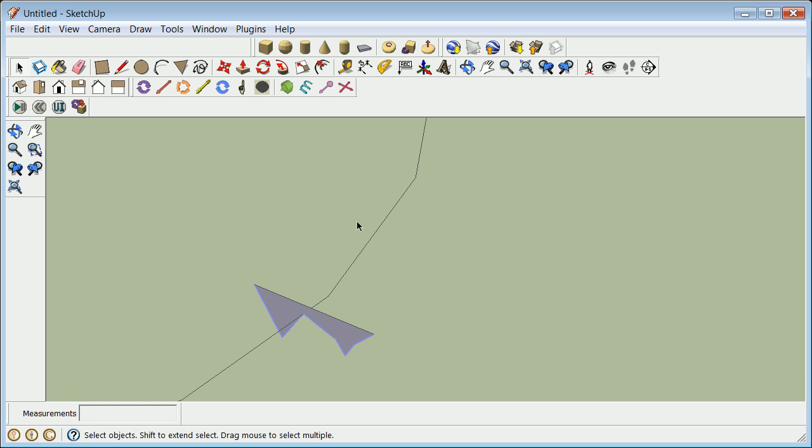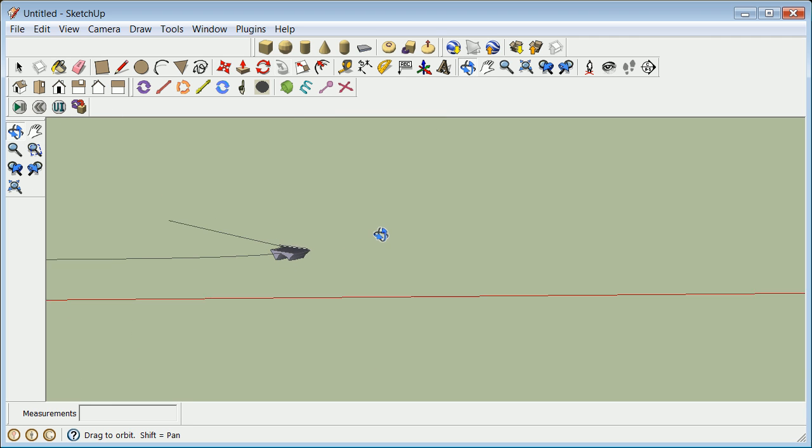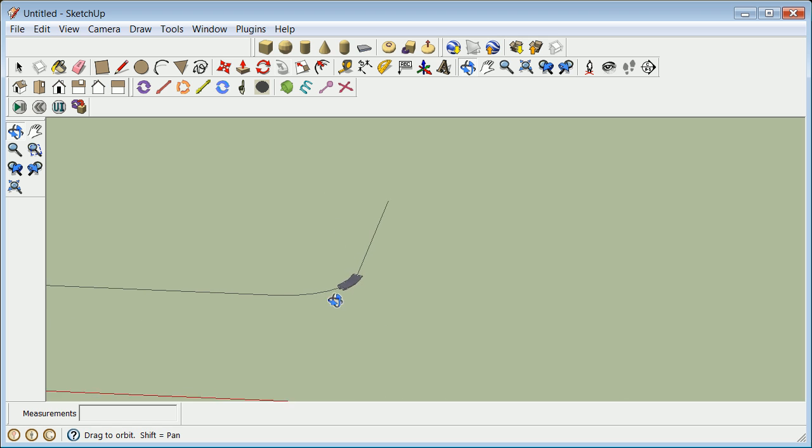and immediately that finds the face, and we're just going to see whether this thing works. I grab that tool there, and then I hit follow me and click that, and you see that it will design at least part of that road section. Alright, and that's typically your extrude or whatever else. Right, so what you'll see in that is, I'm showing you this, it's really not bad in Sketchup and it's actually fun, but I'm pointing out in a preface to the rest of what we'll be doing in Civil 3D and Sketchup and Inventor that the mathematics of transformations, rotations about axes, and translations is going to be something that if you master it, you're going to be much more efficient, not just in dealing with these 90-degree rotations, these 45-degree rotations, but all rotations upon which all of spatial math, civil engineering, survey, mechanical engineering is based.